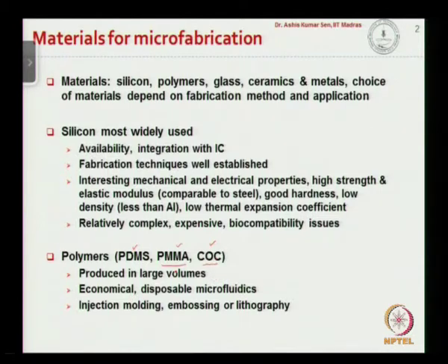The price of polymers is less as compared to silicon, and that is the reason why polymers can be used to fabricate disposable microfluidic devices. Disposable microfluidic devices are particularly applied to diagnostic applications, where we take a chip, bring a sample from a specific individual and test it, and then dispose the chip. That is called disposable applications of microfluidic chips.